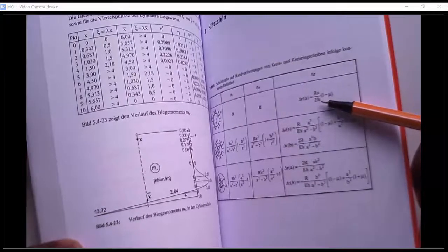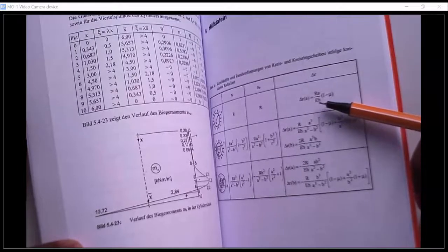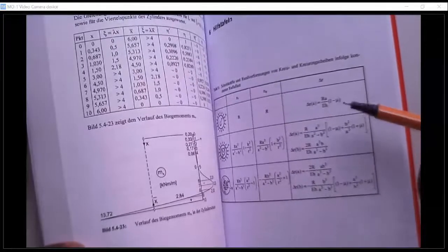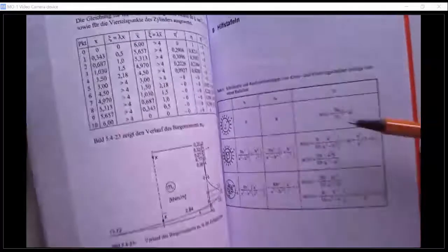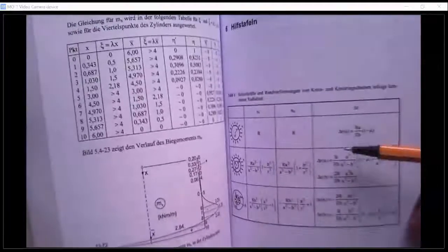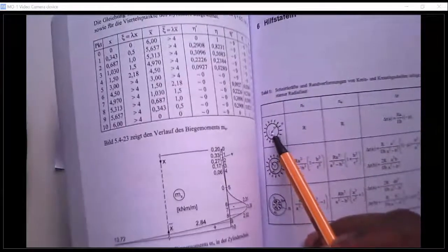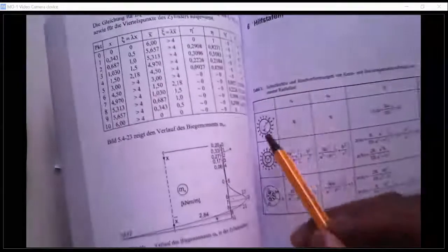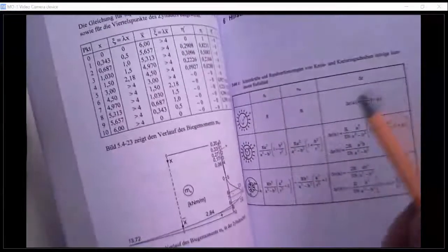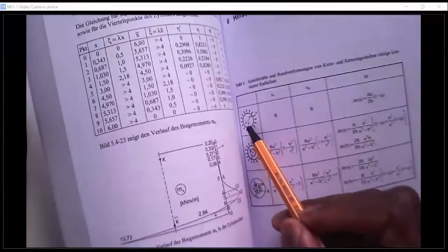They also have something here divided by H. Okay, why is that? We're gonna see what they call H here. It might be the thickness. Times A. Wait. What is that? Okay, at the position A. So if we are at the position, for example, the wall displacement in the radial direction, what will it be? It will be the strain times the original length, so basically the wall radius of the disk, and that's A in this case.